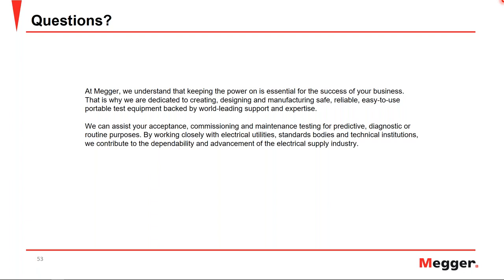There are alternate ways to perform power factor testing in the sense that you can vary the voltage and see how the insulation reacts to the change in voltage, which we typically call the tip-up test. Charles also talked about frequency-based power factor testing, where you vary the frequency and perform the power factor testing to analyze the results in a better way.